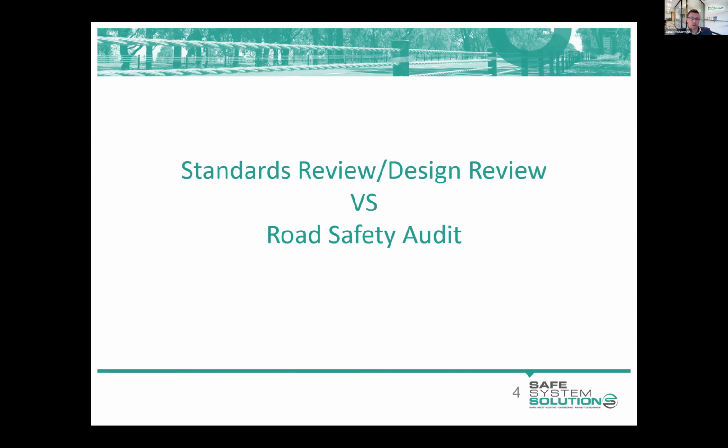As a road safety auditor, you really need to put yourselves in the position of the various road users that might use a piece of road, and think about, would you feel safe? And by all means, if there's a relevant standard that is not being complied with and that supports your view, you ought to quote it, but standards should not be your starting point.